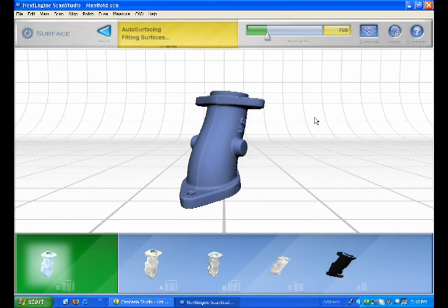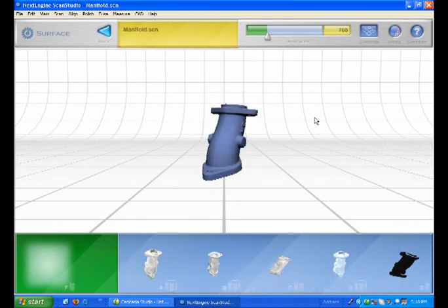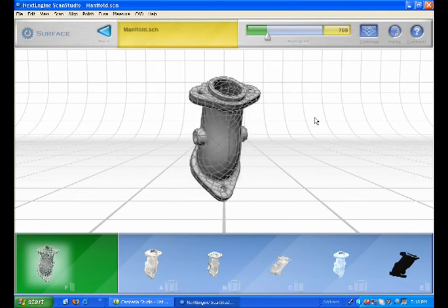We have a spline out tool. We're not going to have time to demonstrate that to you here, but you can create splines and very quickly and easily get spline data from your object and save that out as an IGES or a STEP as well, and bring that into SOLIDWORKS. Then you can loft to the surface or use the SOLIDWORKS boundary surfaces to create the surface of your object.